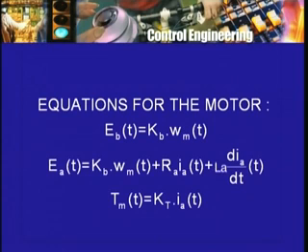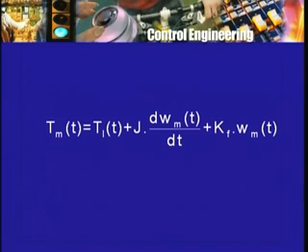That is the effect of the fact that the armature itself produces a magnetic field. Then the electromechanical interaction equation, like the back EMF equation, the other equation, motor torque produced is equal to Kt into Ia, and the mechanical equation for motion of the system, namely the motor torque equals the load torque TL plus the accelerating torque J d omega m dt plus the frictional opposition torque Kf into omega.